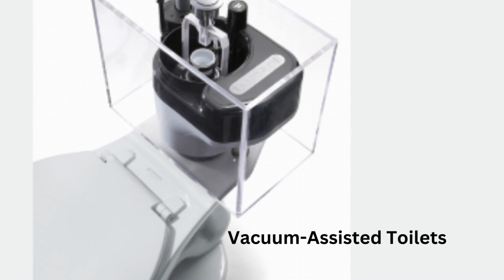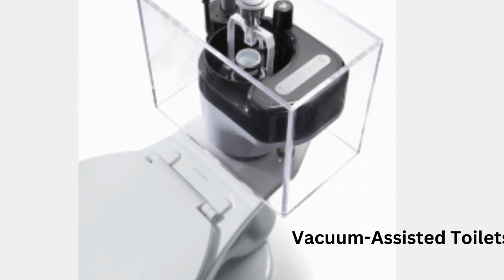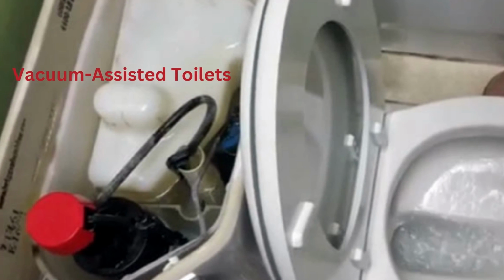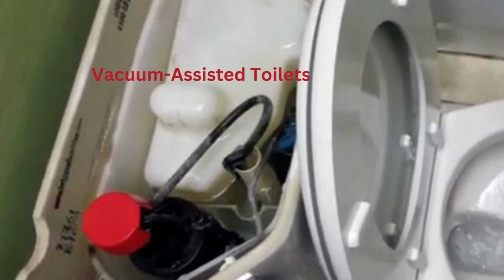When a user flushes the toilet, the flush valve opens and water flows into the bowl. As the water level in the bowl rises, it creates a seal that traps air inside the bowl. The vacuum pump in the tank then removes the air from the bowl, creating a powerful suction that pulls the waste and water out of the bowl and into the drain pipe.